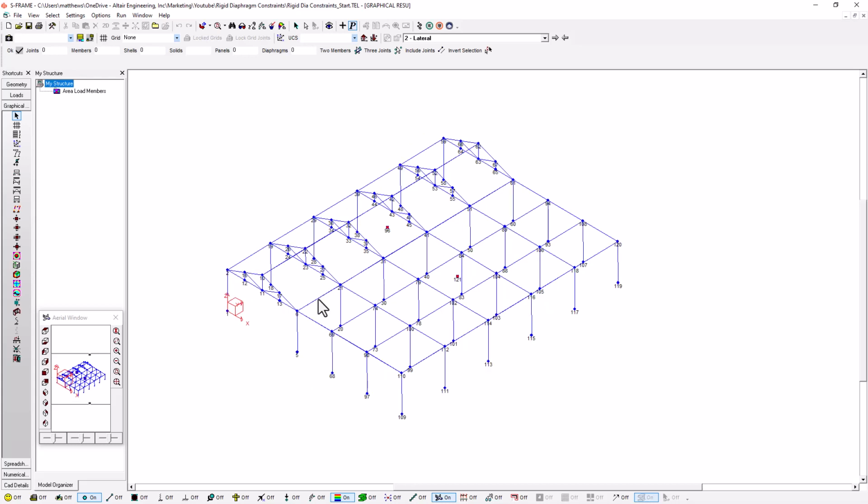And how do we get around this? Well, first of all, the solver is already ignoring the constraints for one of these panels. It's saying panel 1 constraint is being ignored because of this particular shared joint behavior. But if we didn't necessarily want it to ignore the panel 1 constraints, we could always control which joints are included in a diaphragm constraint or which ones are going to be excluded. For example here, I'm going to remove from the flat panel these 6 joints from that diaphragm constraint.